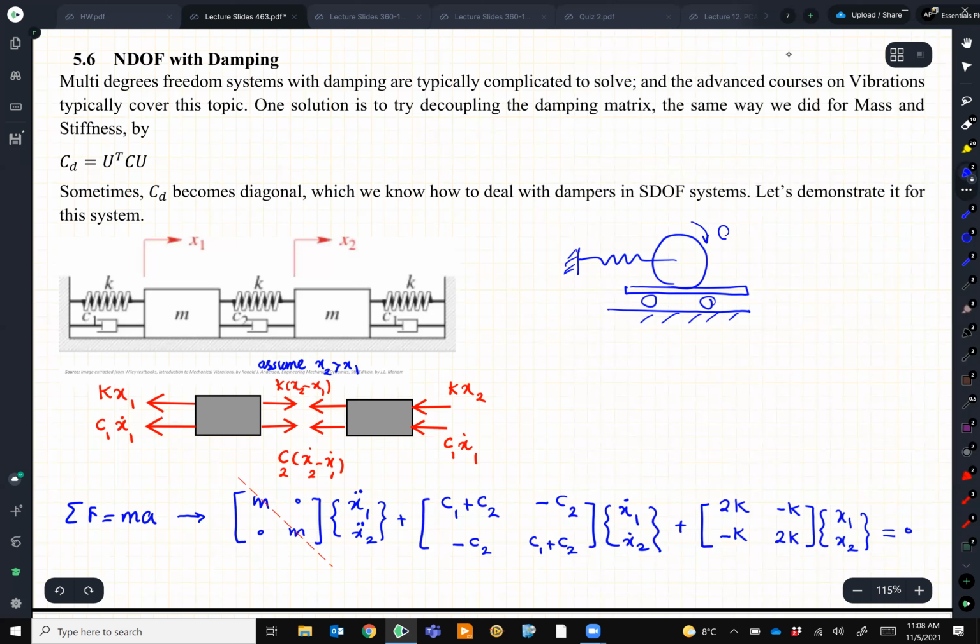So this one is going to rotate with theta and this one is going to move with x. If you remove the spring, theta and x are connected, right? So it means when you write your equations later, you're not going to end up with 0 on the off diagonal. So a quick check always: remove the spring, remove the dampings, and move one of them. See if moving one of them results in moving the other one. In the example that we have, it's not.